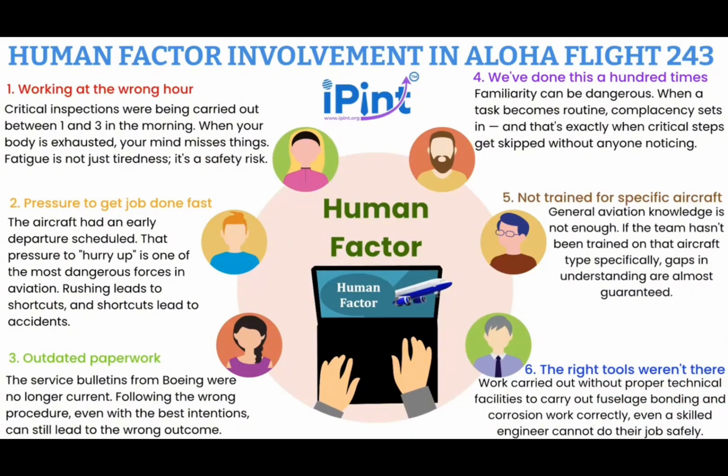So what does Aloha 243 teach us? It teaches us that accidents are rarely caused by one single failure. They are the result of multiple human factors combining: fatigue, pressure, complacency, poor training, and inadequate resources, each one chipping away at the safety margin until there is none left. That is why we study human factors, not to assign blame, but to understand and to do better.